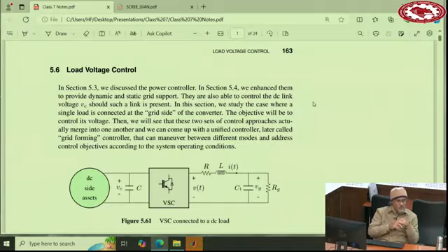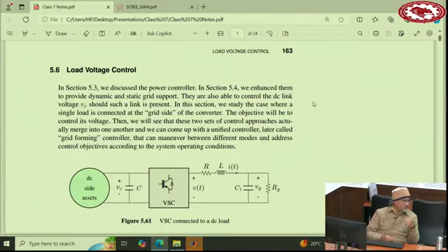So there is a grid, you just feed to the grid, or you follow the grid and support the grid. If the grid goes up and down, has some fluctuations, you support the grid, either inertia or static support, droop support, or both of them, right? So terminology is not very accurate, so I cannot say what is the difference between grid following and grid supporting, but the concept is clear. The assumption is there is a grid that supplies a voltage, and now you are feeding power to that grid, either without support or with some support.